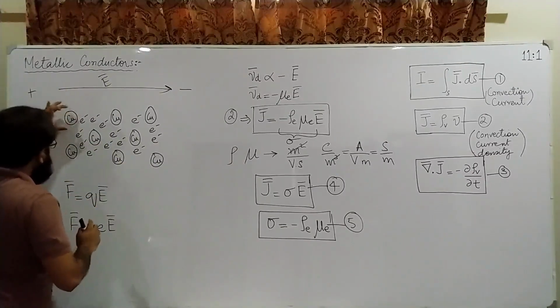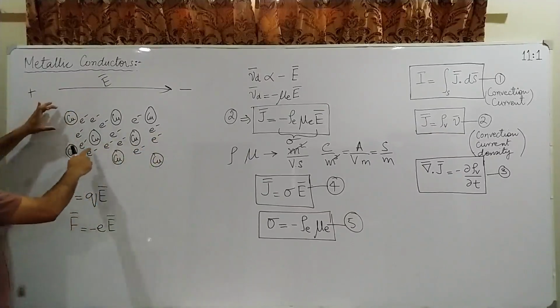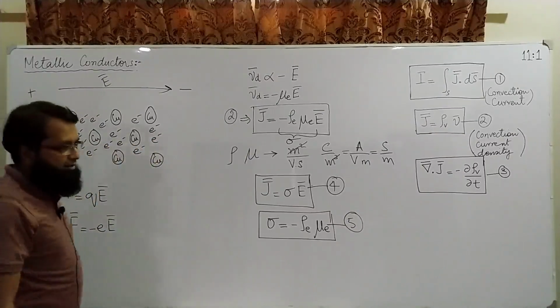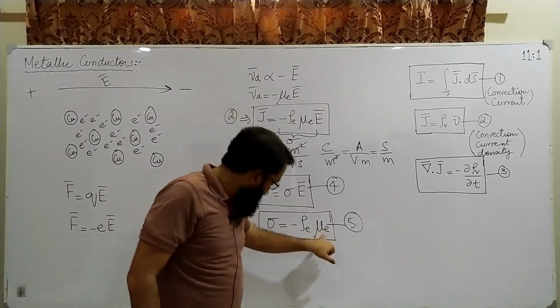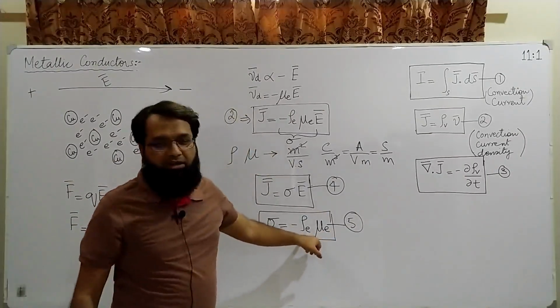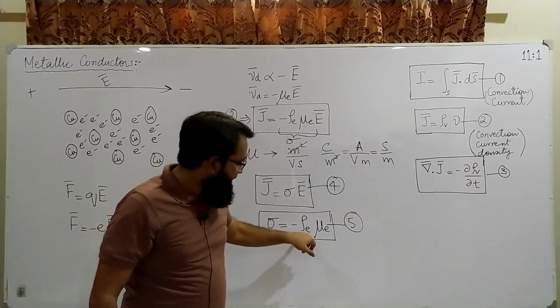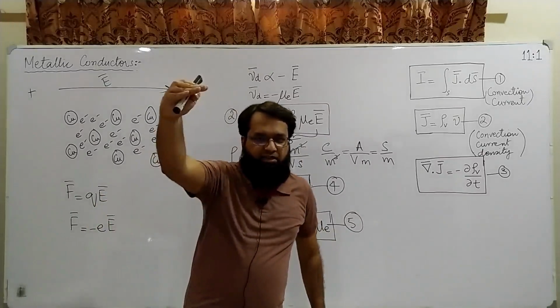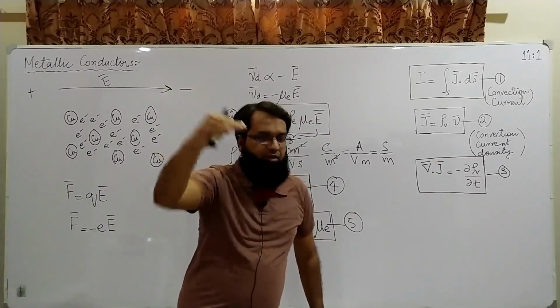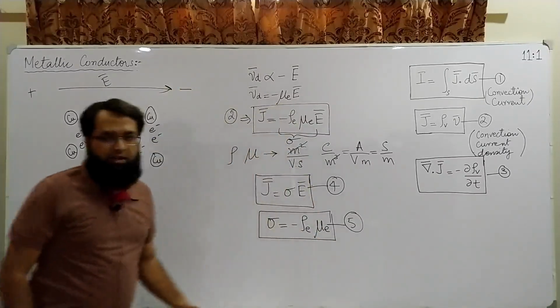Increased oscillations mean that the ease with which electrons can flow through the crystal structure will reduce, and this reduction is actually significant compared to the increment in the charge density. So with the increase in operating temperature, the overall conductivity reduces.